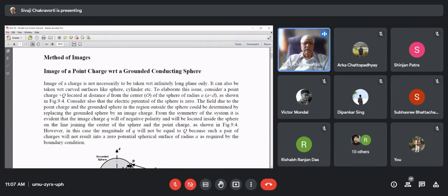One of the spheres is typically at the high voltage, the other one is earthed. This is the typical sphere gap arrangement which is used in high voltage engineering extensively all over the world. This is used for measurement of voltage, for calibration of equipment, and so on. And this is also used as a very fast acting switch.